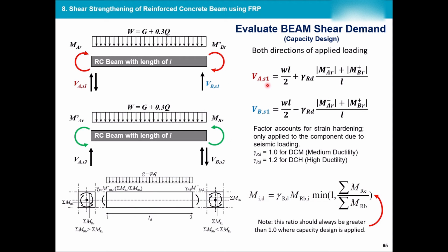If you can't remember this, please refer back to the courses that we have in Introduction to Seismic Design or Eurocode 8, and you can figure out how to calculate the new shear. I have given the formulations here. It's not very sophisticated. Majority of the softwares actually do this automatically as well. So the shear analysis that you get has already considered these.